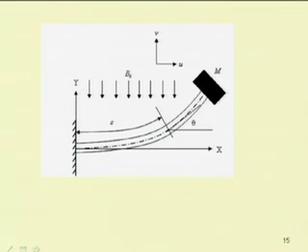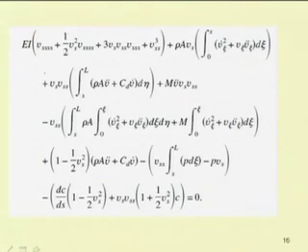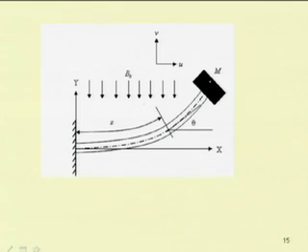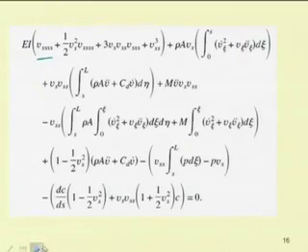So, in this case of this beam, if the displacement is large, then one can model this as a system like this. So, here if one takes only the Euler-Bernoulli beam, one can have only this term, that is EI del fourth V by del S fourth, plus one more term, that is rho del square V by del T square. So, we can have only two terms in case of a linear system, but in case of this nonlinear system, when you are considering large displacement along with this force due to this magnetic field, the equation can be written in this form. So, detail of this thing we will study later, but one can write this equation.